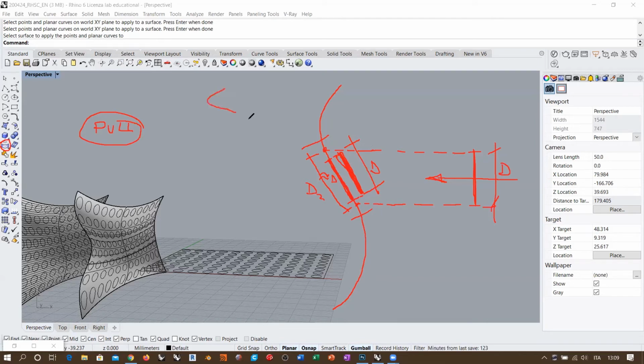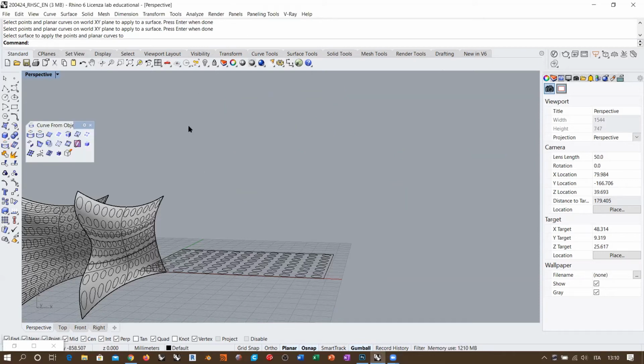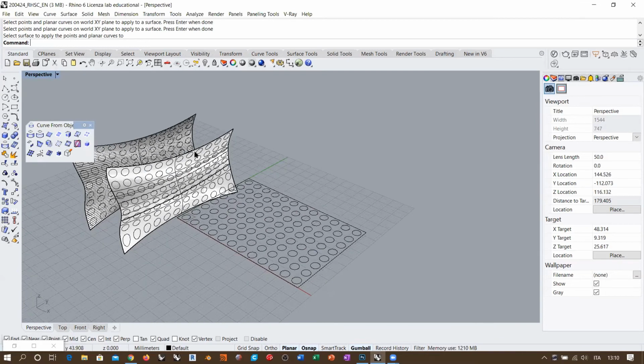Because if your surface is like this, and you want to apply the text from here to here, there is no way to control that deformation, because this part of the surface is oriented like this, and this one like this. So the pull will use this normal direction, which are basically radial, while you are working with a flat geometry in order to project it onto the surface. So it's impossible. This is absolutely impossible. Okay, so that was extremely clear. Yeah, in both cases you can have control, but in this case it's topological control. In the other case it's geometrical, but you always have limits.